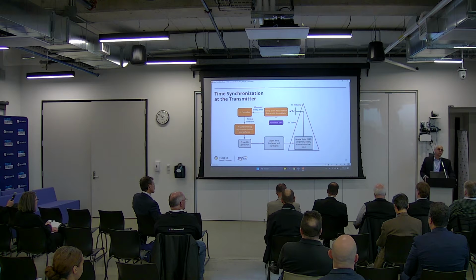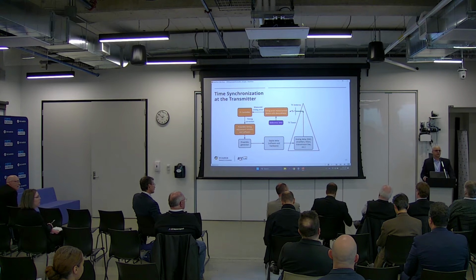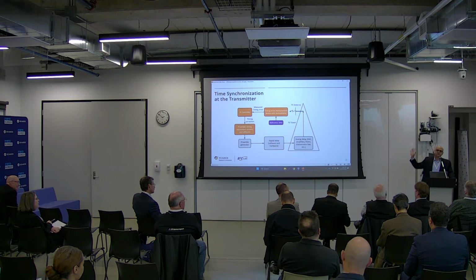And people who have worked on control theory know you don't always just take the error directly, or the loop becomes unstable. There are techniques, and people have been working on them for 70, 80 years. You can have a loop filter or some sort of controller in there that averages the error and feeds it back into the system. And that is actually the loop.